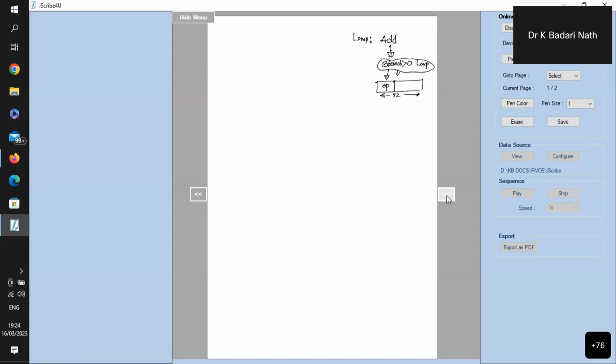Next, I have to encode in this instruction one piece of information, that is, the address of the place where I am supposed to jump, the loop. If I include the full address of the memory location where the loop is associated, it is 32 bits. That means the instruction size will exceed 32 bits, because I cannot accommodate the complete 32-bit address here.